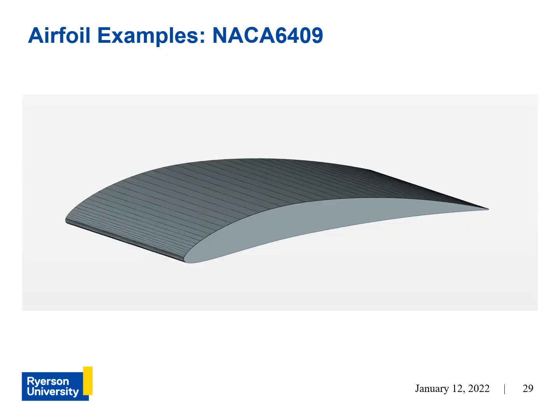The NACA 6409 is more forgiving to manufacture because the airfoil is the thickest out of all the ones that we talked about so far. And here's a picture of the NACA 6409 in terms of a 3D depiction of it. So it's good to consider your method of manufacturing when selecting your airfoils. Choose the airfoil that best suits the means by which you're going to make it.